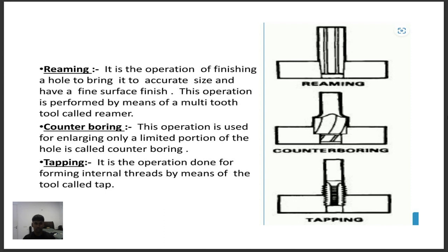Counter boring. This operation is used for enlarging only a limited portion of the hole is called counter boring. Tapping. It is the operation done for forming internal threads by means of tool called tap.